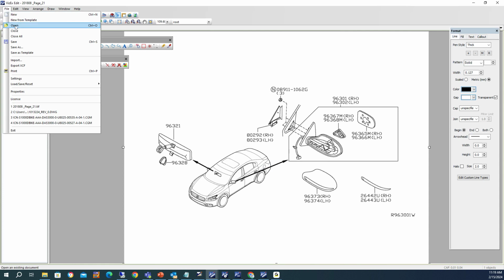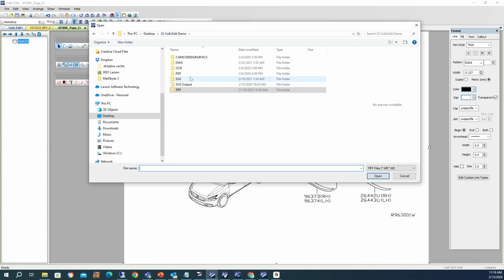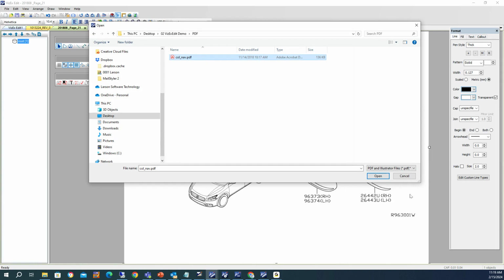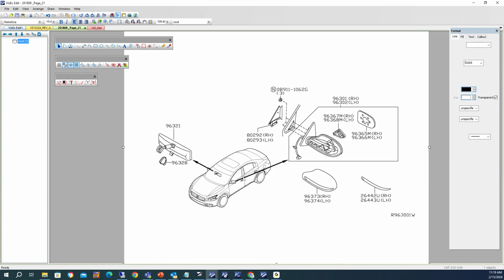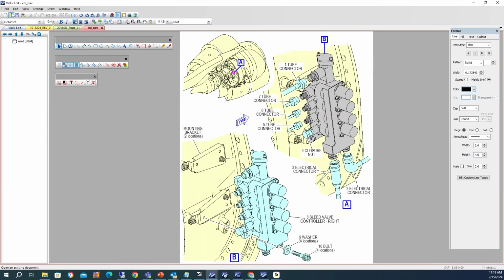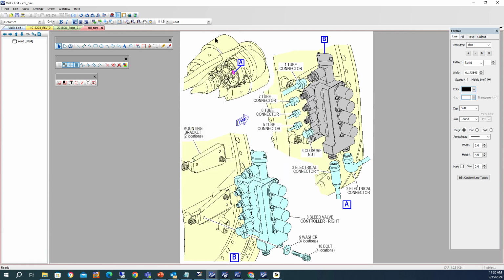And again, PDF. So if you've got PDF files as your only way back to creating from a legacy file, I can open a PDF file here and then resave it as a CGM file or an SVG file. So we'll just save as now, and I could save this as a CGM or SVG if I needed to make it standards compliant. And also, if it's a vector file, then I could again work with the graphics.